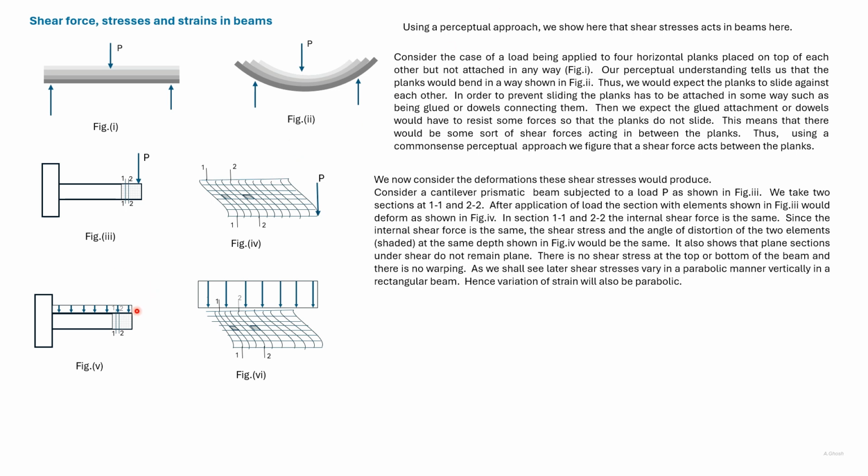One would note that the shear force in the section 1-1 and 2-2 will not be the same. Here again, in figure 6, this portion has been expanded. Again here, two elements which are shown shaded are taken at the same depth. However, since the shear force is not the same, the shear stress on these two elements will not be the same. Hence, the angle in these two elements will not be the same.